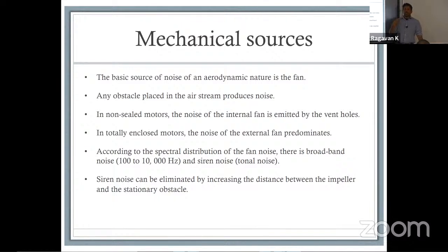It causes air to flow through the motor. So anything that you have along its way is going to create some noise, right? So that means if you have a non-sealed motor, the noise from the internal fan comes out from the vent holes. If you think about it, it's like a flute. You are essentially trying to control the different orifices that are available.